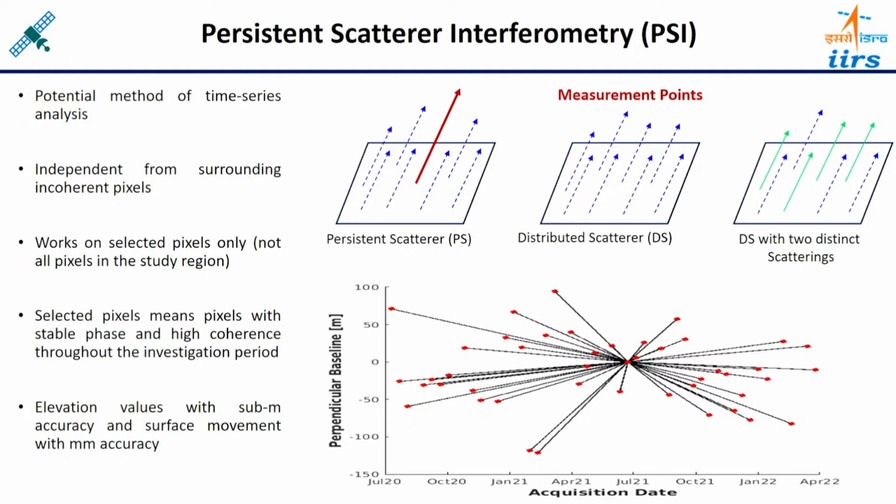Suppose you are working in a forest region: in 5 years the canopy structures of the entire forest will be different. If it is changing, it means the signals between the first image and the image after 5 years will be completely decorrelated. It means that pair is not suitable for interferometry.